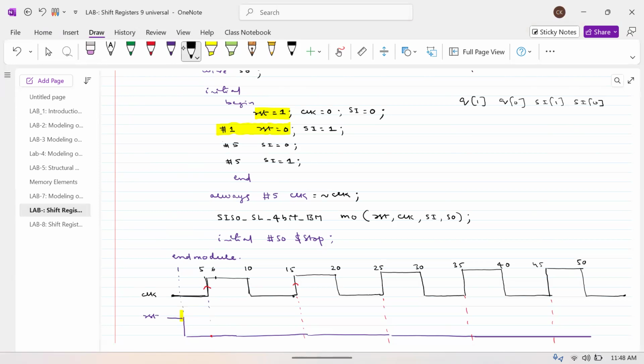Okay, point is clear. So therefore this is what is important for us. Now, how can we write this information by using a concatenation operation? Something like this we can write: concatenation of q 1 down to 0, and si. Simply I can write si is actually a 2-bit data. I have to declare si as a 2-bit data. If you're not writing the 2-bit data, if you write like this, then it's wrong. Please remember that, right?